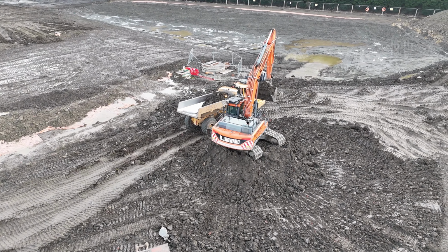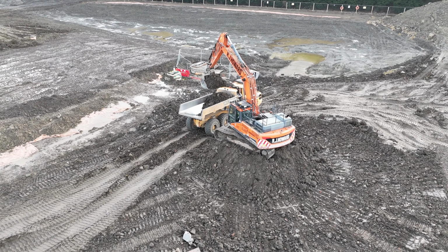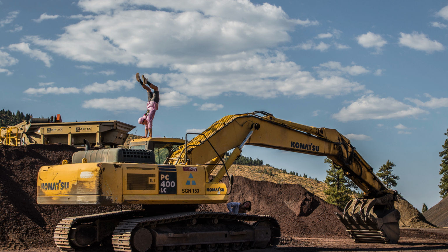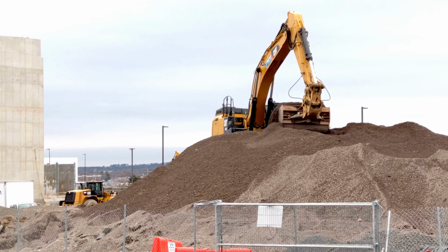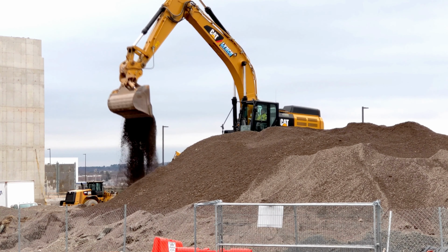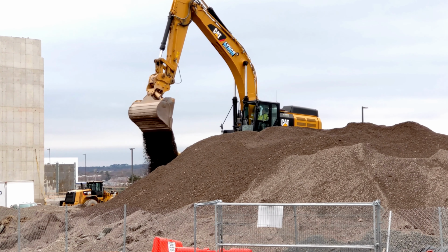Another important factor contributing to excavator stability is the undercarriage design, particularly in crawler excavators. The wide track base and long track length create a large support polygon on the ground. This increases the machine's resistance to tipping by distributing loads over a broader contact area. The track structure also lowers the overall center of gravity of the machine, further improving stability during operation on uneven or sloped terrain.